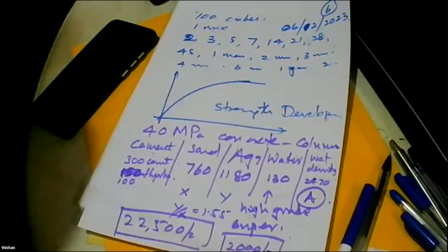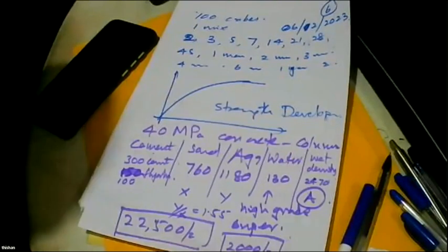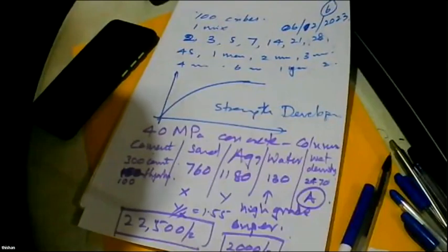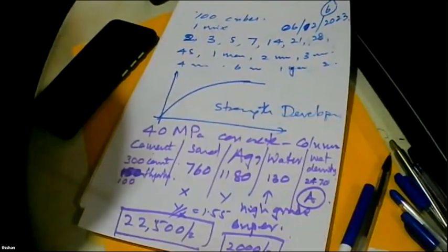What is that? Steel? That hollow pole? That is pre-stressed concrete. It's not reinforced concrete. So that's why they wanted 65 megapascal in 24 hours to debond it. Do the debonding. Right? Okay. So it's a pre-stressed concrete pole. So it's a hugely stressed curve. So it's a stress pole. So it's very strong. You would have seen this used by Sri Lanka Telecom.